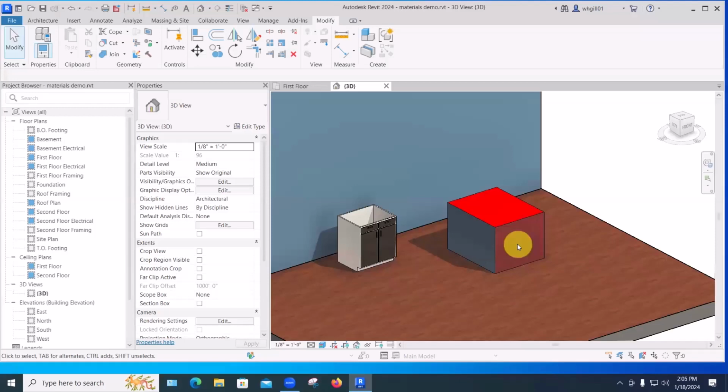One thing we need to understand is how Revit deals with images that are brought in. The image files are not stored in the Revit model itself, but on disk, and Revit needs to be able to find them when it comes back to render something a second time. If we define a grass material using a photograph called grass.jpg, and render it, it looks fine.